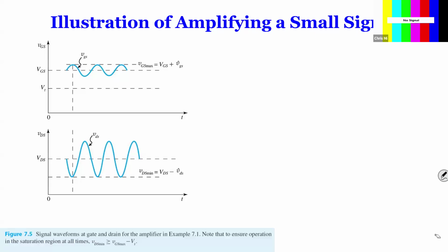Now, in real life, you might say, okay, I got a small signal input and I got an output, but the output has a DC and an AC. How do I separate these two? If you're in the lab doing an experiment, you'll find it's easy when you see it on the oscilloscope, there's a button between DC and AC choice. You put DC, you'll see the whole thing. You put AC, it will automatically take the DC out. You will see this cross zero, actually.